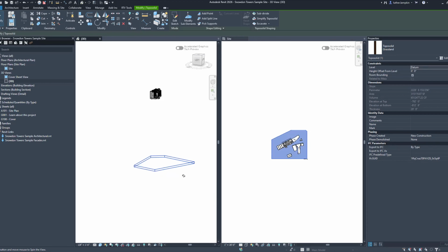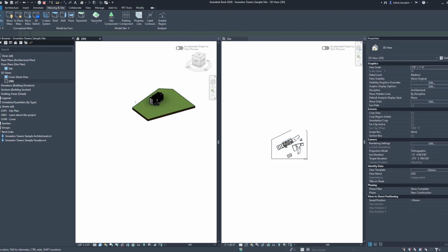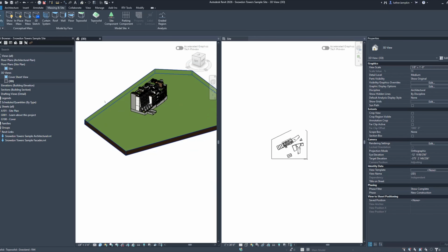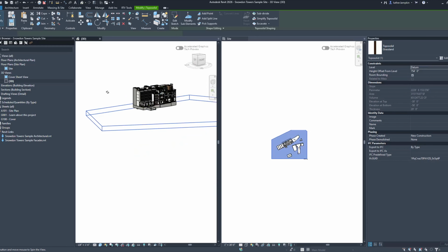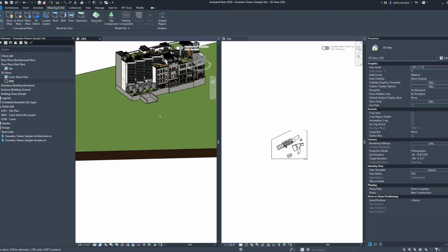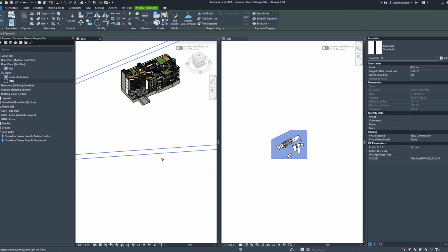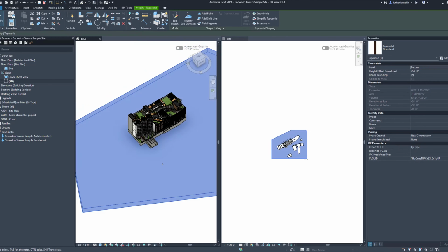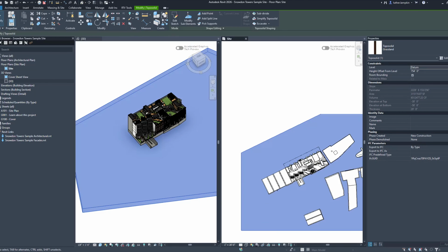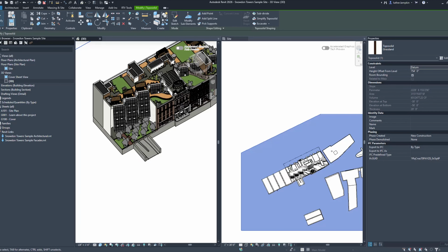Because sometimes, like I said before, you remember what it said when it was datum? It was 754. So guess what? 754. See, this is why we wanted to do this, to show you the process, show you what's going on. So now I changed the datum, and now I'm back at level because I remember what it was before, right? And so now, as you can see, this is why you want to work in 2 planes to be able to see what's going on. Because see, in the floor plan, it looked like I was perfect, but in the 3D, I knew that I had some work to do.